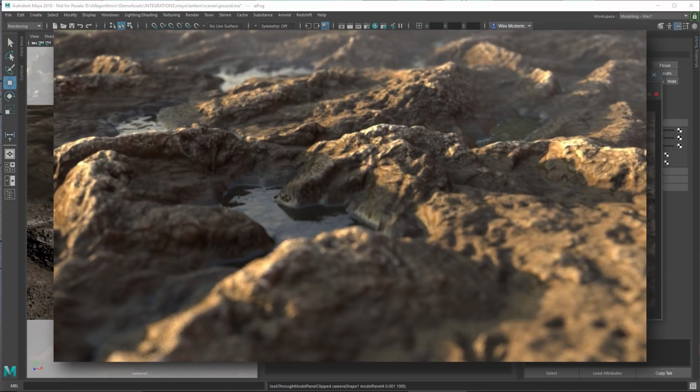In this video, we quickly set up an entire scene to do some displacement rendering using the height output from our Substance. We set some subdivision properties on our ground plane mesh, and then fed the height into the displacement material of the shading group of the Arnold standard surface material.